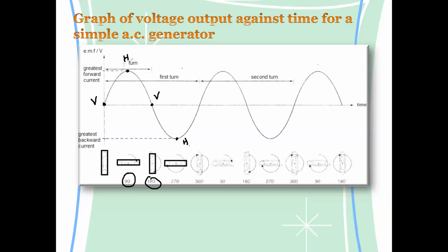But what is the reason why? Here we have a positive voltage example, and this one we have a negative voltage. The reason is the rotation of the wire, the reference rotation of a wire is different. Like if I say this is a shaded part, initially it was moving down, and now this shaded part is moving up. So the side of the wire which is moving has changed. That's why the direction of induced current will be different.